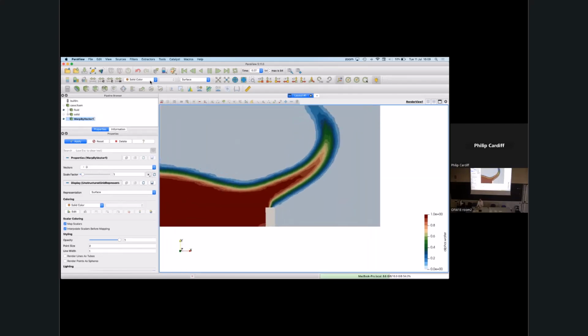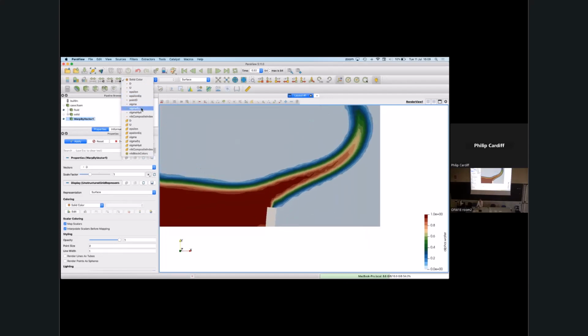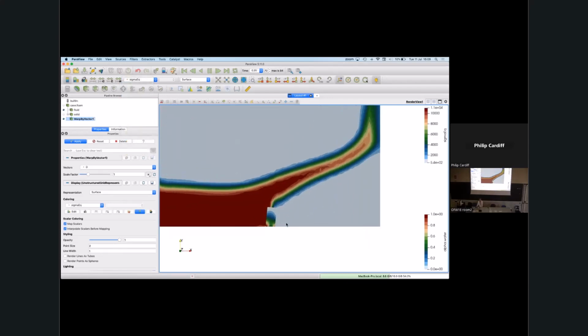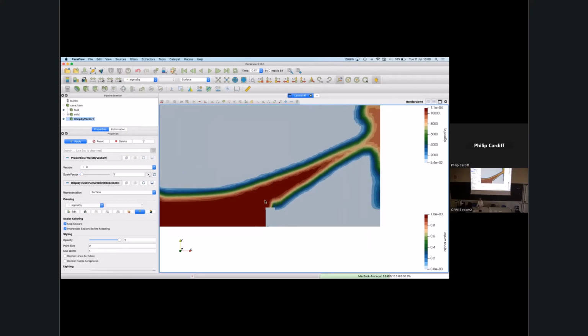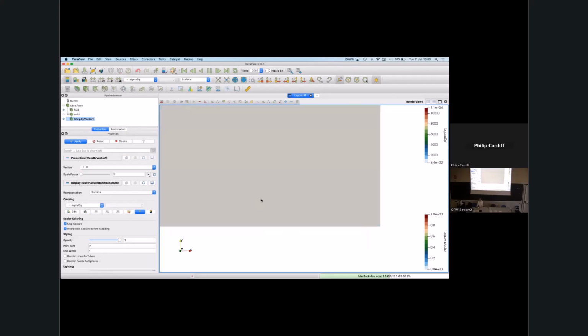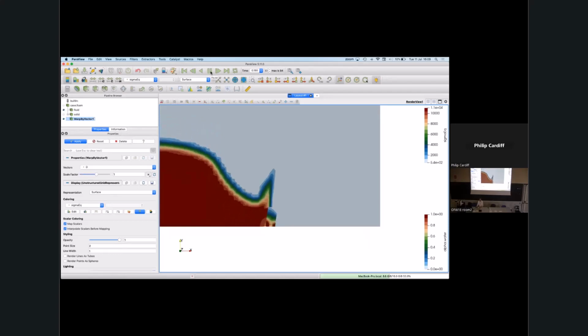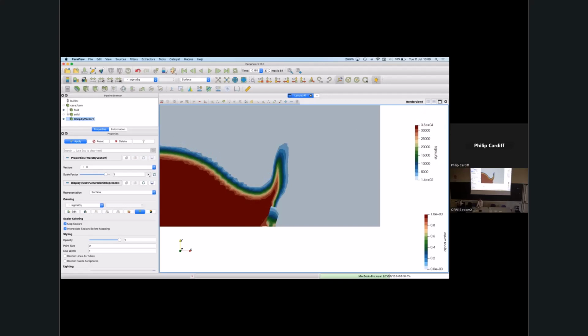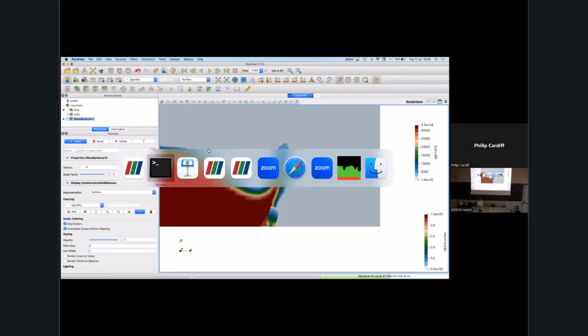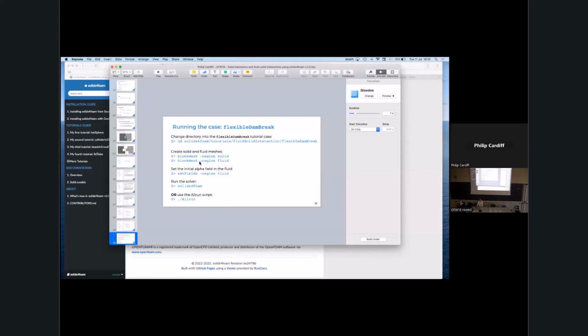Good. So we can look at things like the von Mises stress. So classic bending, the high stress is at the outside, particularly at the fixed region. So you get a high stress at the bottom. So if we change this to a plasticity model, then you might expect plasticity in those regions. So if we look at the maximum stress, okay, it's very, very small, 33 kilopascals. Fine. Okay, we'll keep going.